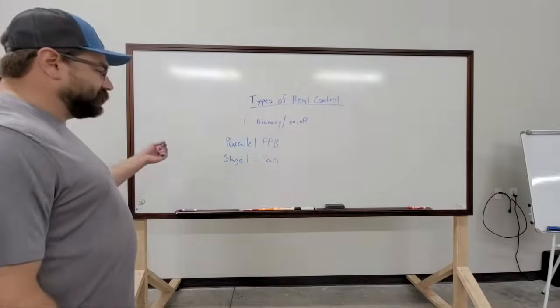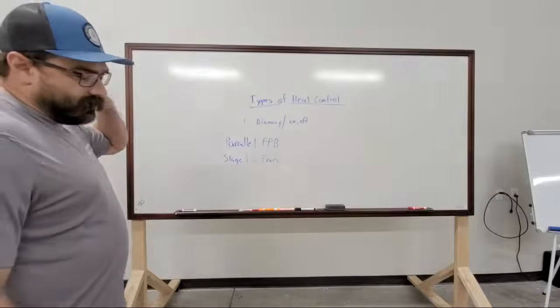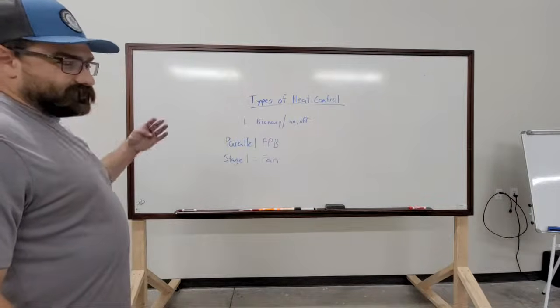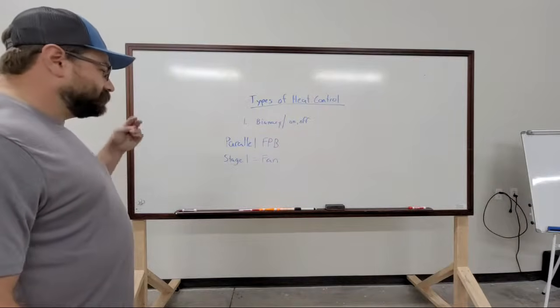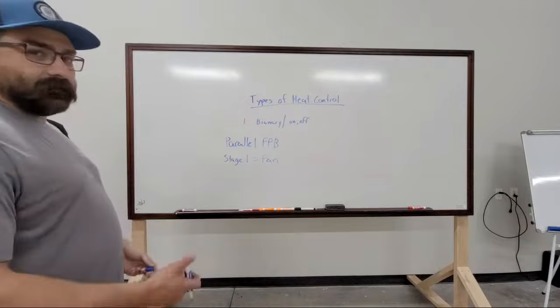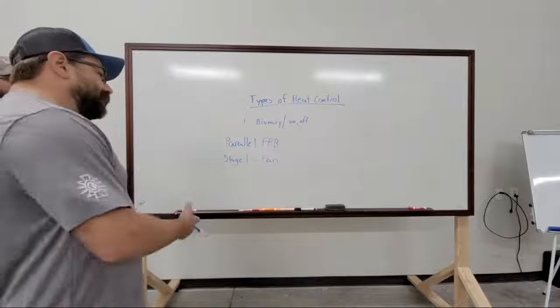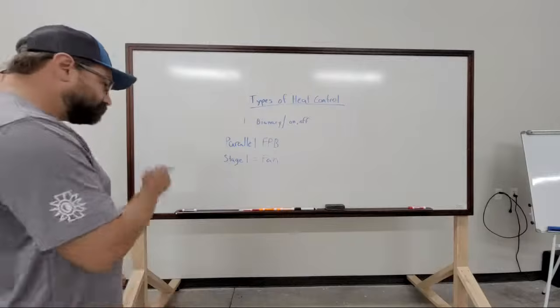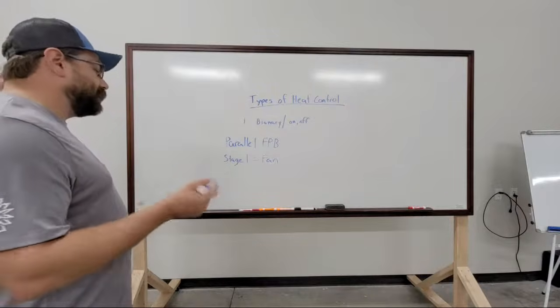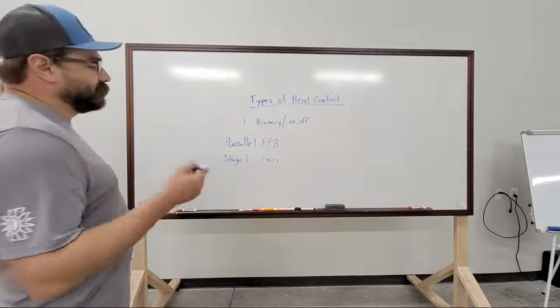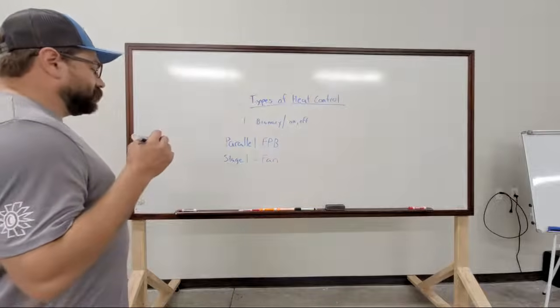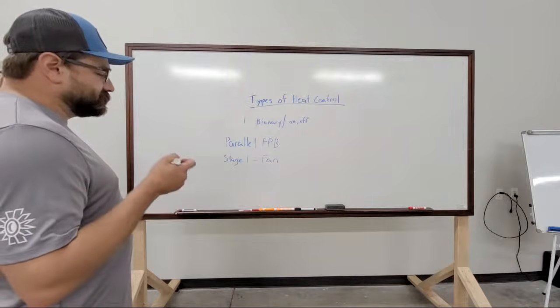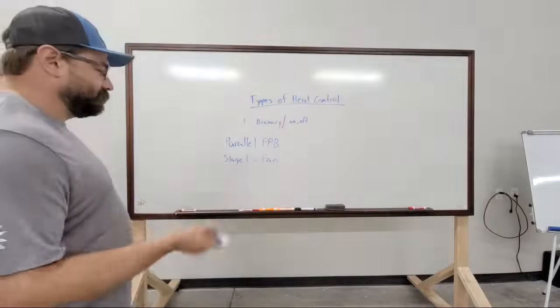The idea is that it will draw in return air and use that, which is at a higher temperature than space air, to try and bring the temperature up in the space without actively going to heat. Not every box is configured that way. Some of them bring them on simultaneously, but sometimes, more typical than not, your fan is your first stage of heat.